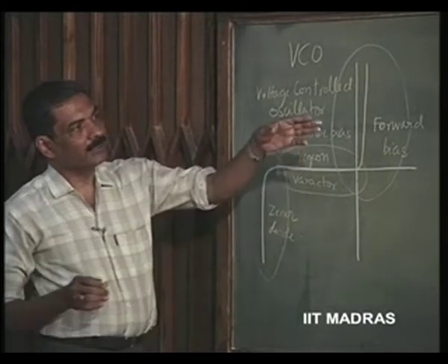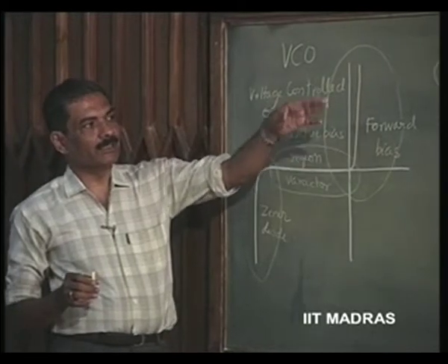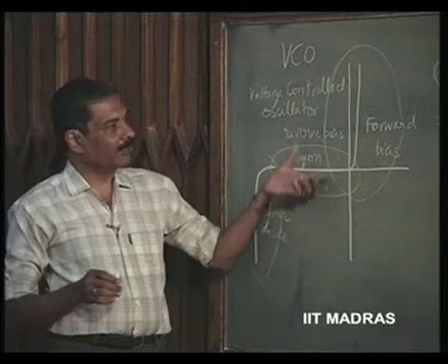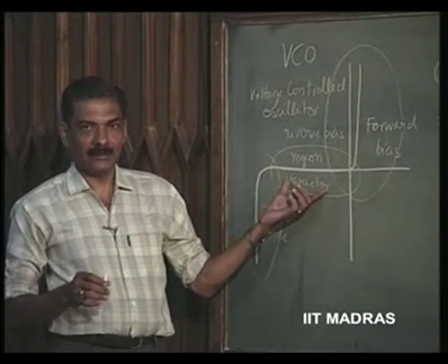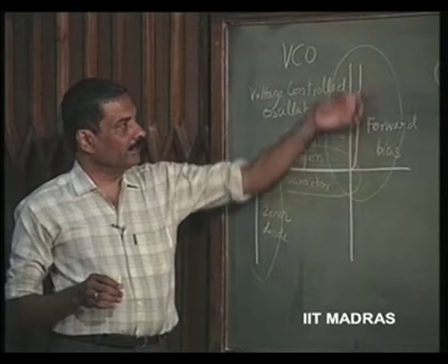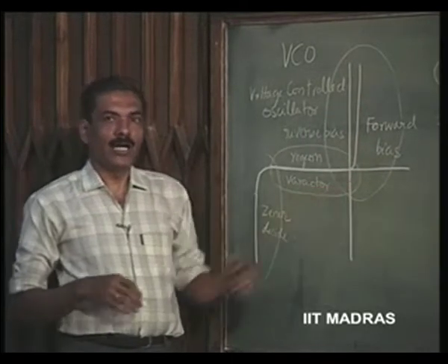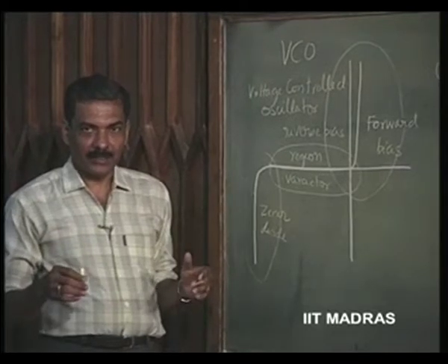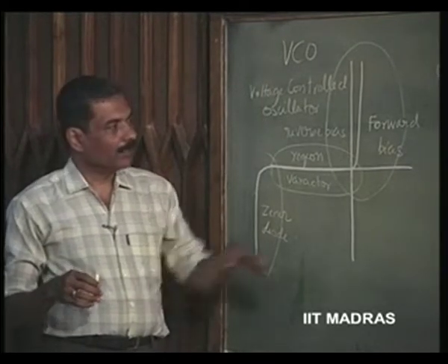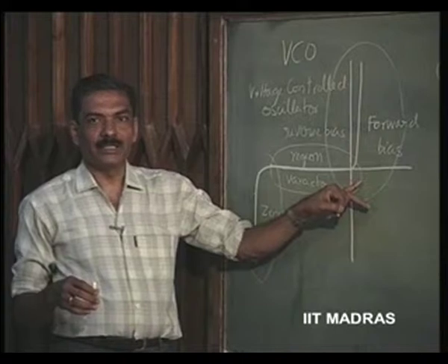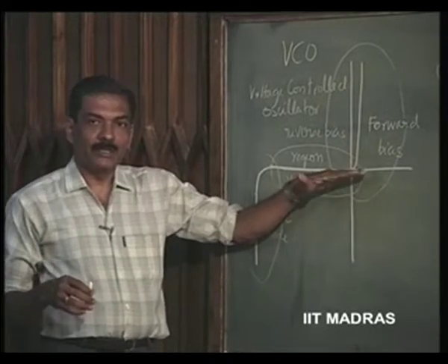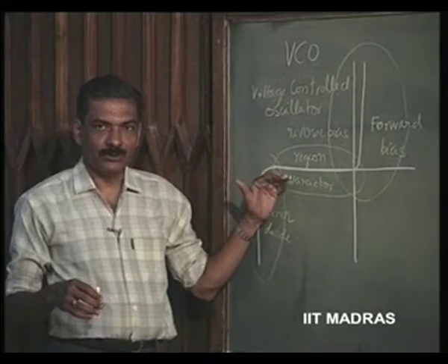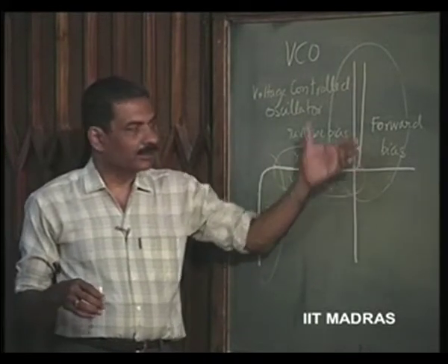Here he will maximize the ratio between C max to C min, and specify what value of maximum capacitance it has. And then here he will say at what forward current it has to be operated, what is the average forward current, repetitive forward current, all these things when it is being used as a rectifier diode. What should be the peak inverse voltage rating of this if it is to be used as a rectifier diode. These are the different ratings.